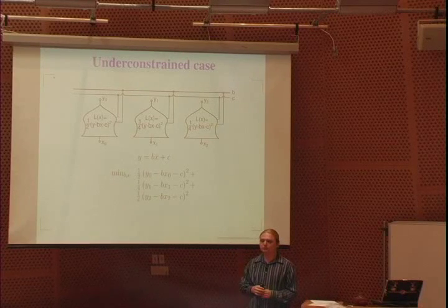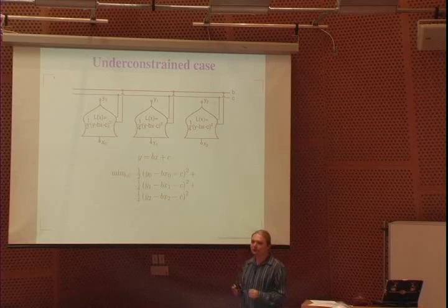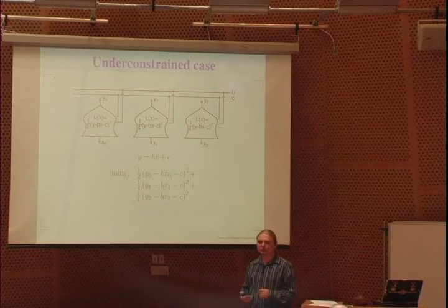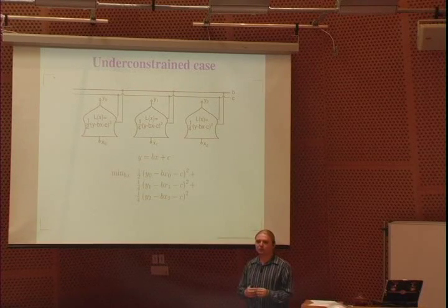What about capacitance within the blocks? I'm wondering about the ability to split them into three like that. The capacitance, you handle that. So right now we're operating at low enough frequencies that we're assuming the capacitors within the blocks are small compared to the capacitors outside of the blocks. We're assuming they're essentially instantaneous.